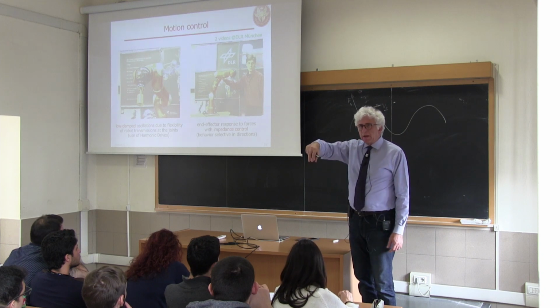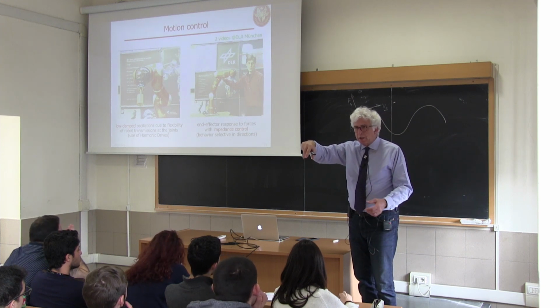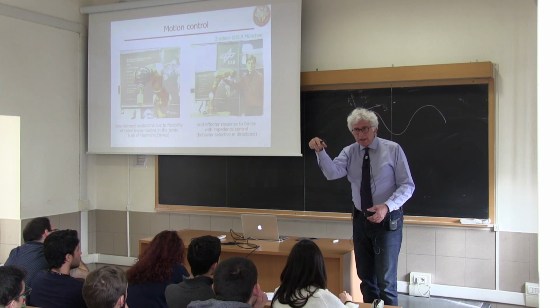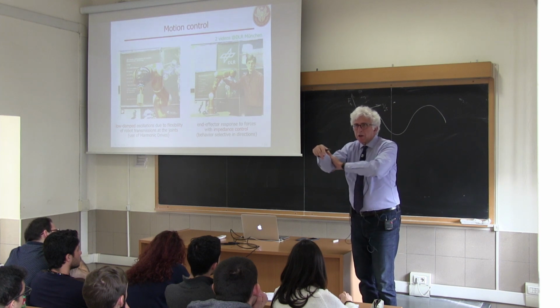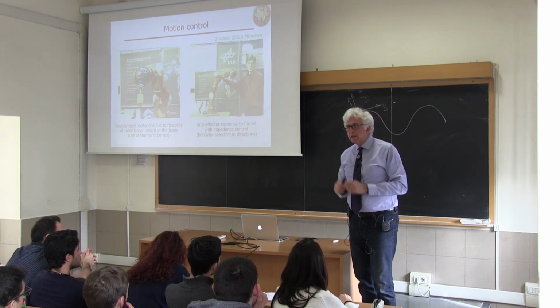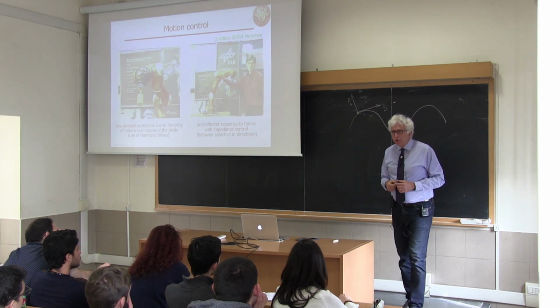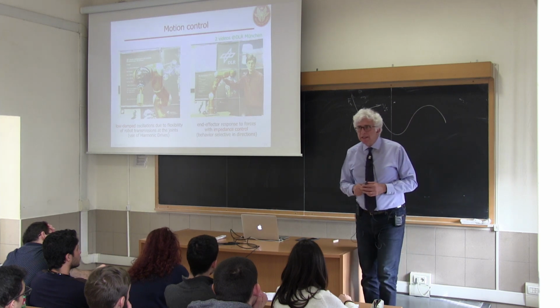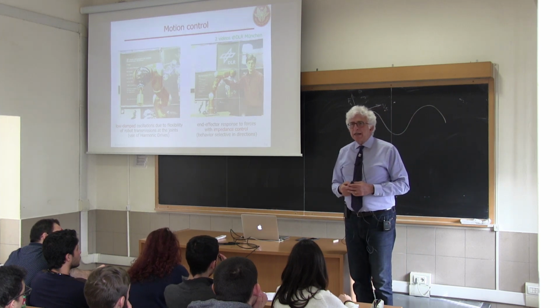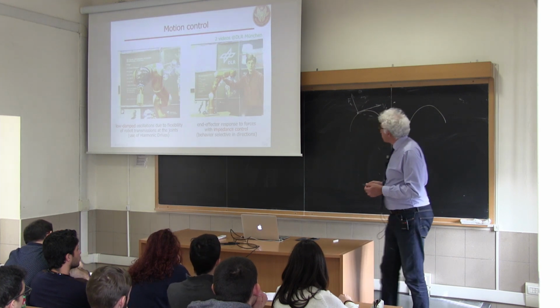You have a 7 degree of freedom robot that has to keep the pose, which is a 6-dimensional task, position and orientation, but there is some internal motion that can be achieved, and by pushing on the structure, the controller keeps the end effector at rest in the given position, and you explore what is called the self-motion of this structure. We will see this in detail when we attack the first topic related to kinematic redundancy.